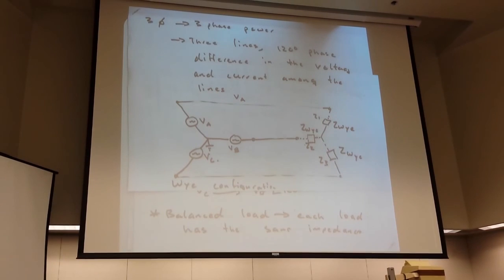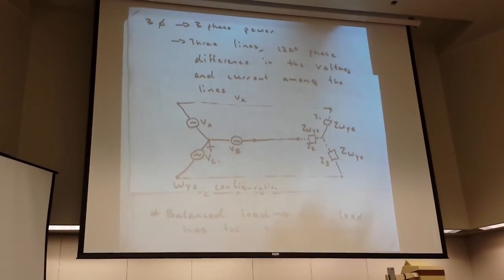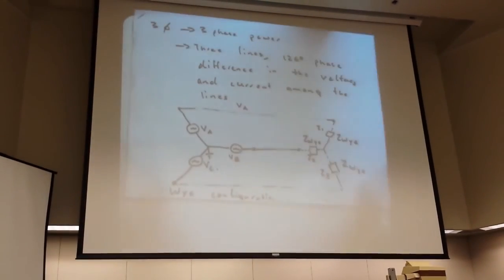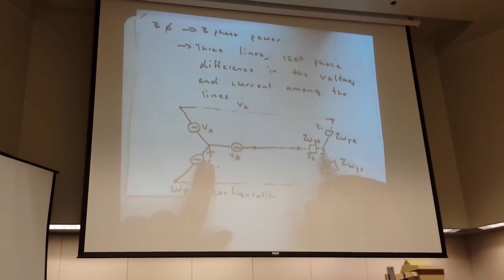Well, if it is balanced, when you look at this, this becomes a single phase system. So everything that we're doing here with three-phase, if the loads are all the same, well, there's the ground, here's the source, I trace my loop, and we can throw a little ground in there. And that little VA loop is a single loop with a VA with a phase of 0 degrees.